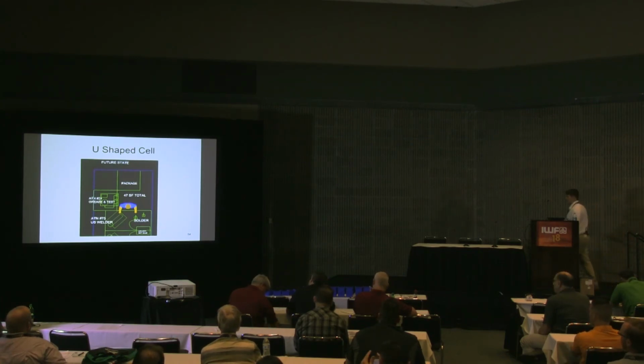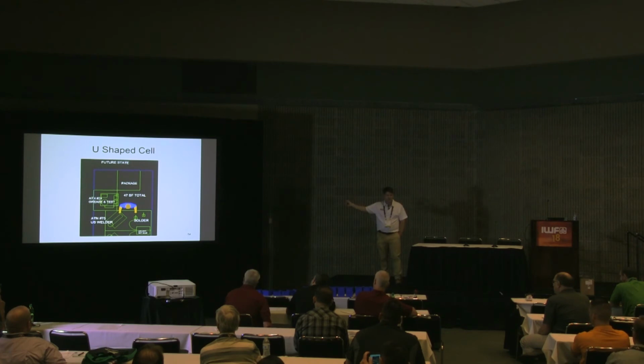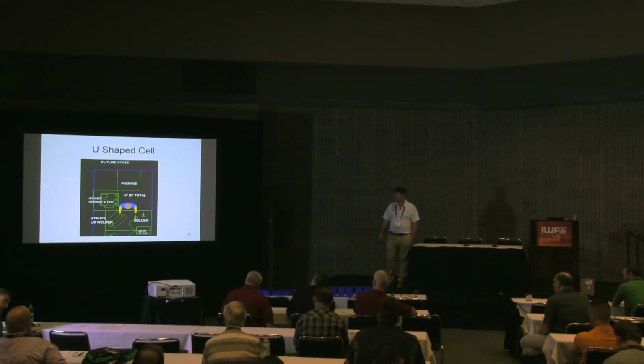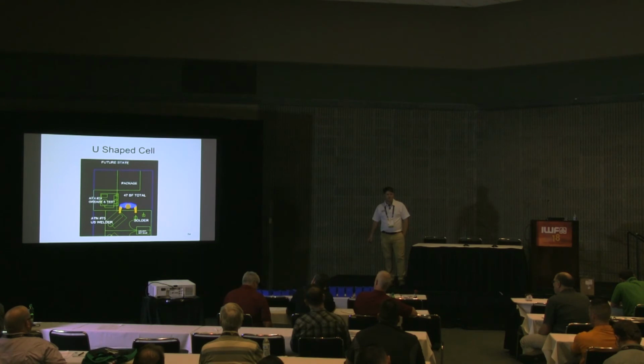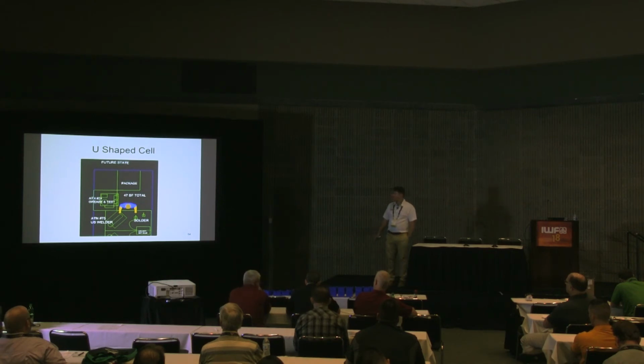This U-shaped work cell, this is one I did for a lighting assembly. Very small. These 3 pieces of equipment used to be spread across the entire facility. We put them all right next to each other. Grease and test and solder. 1 minute and 47 seconds cycle time per light. It used to be like 4 or 8 minutes depending on when stuff got moved. It would take 18 days to make one lighting assembly for a truck trailer lamp. Like, it's less than a minute, right?